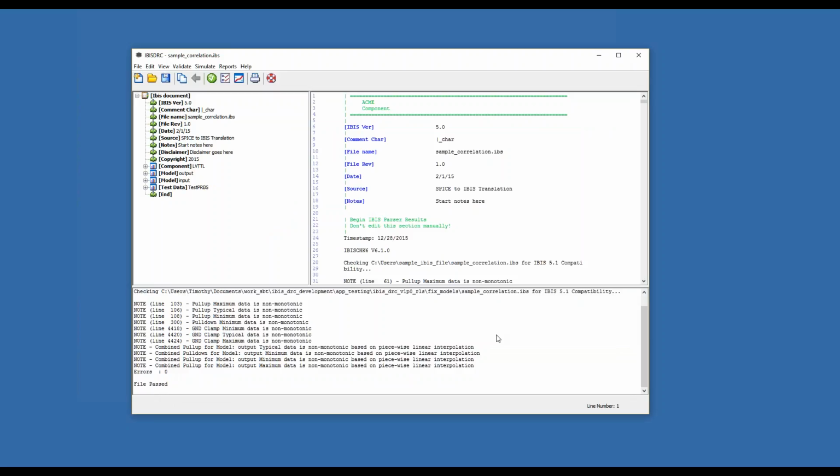Some of this is just an automated flow, but I think you can see that you can run your own simulations no matter how you're going to do it and compare it to something. Just take the edge rate of your simulated IBIS model, go in the lab, look at it on whatever bench you have, and see if it's within 10%. So you can always start somewhere to look at the IBIS model quality.